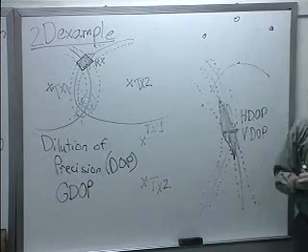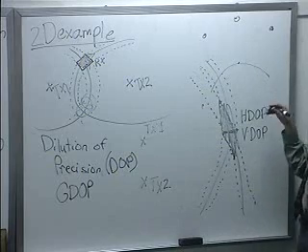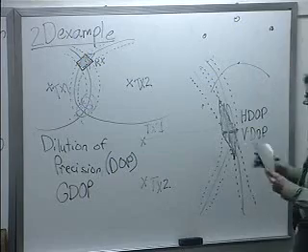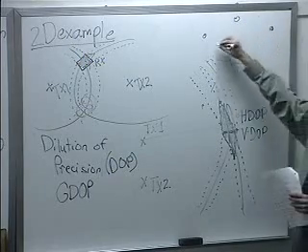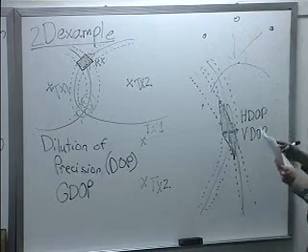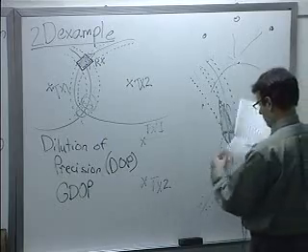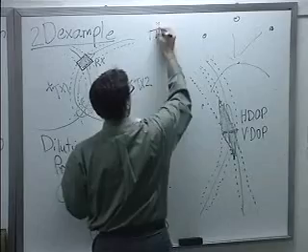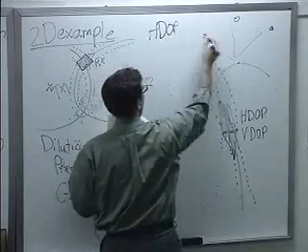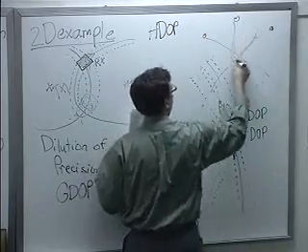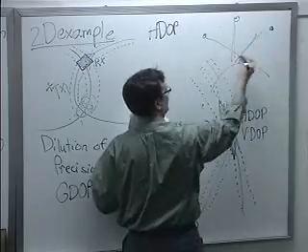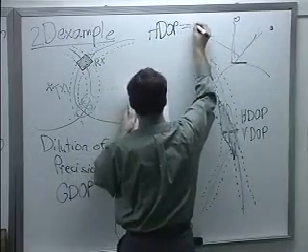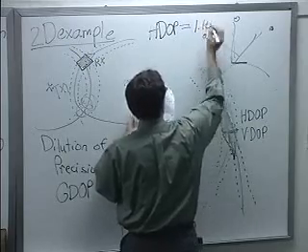So based on the formula that I put over there on the board, the typical GDOP that you would multiply by for an average set of GPS satellites above you: well, the HDOP turns out to be pretty good because you've got some spatial variety across here. So your horizontal dilution of precision is about 1.16.